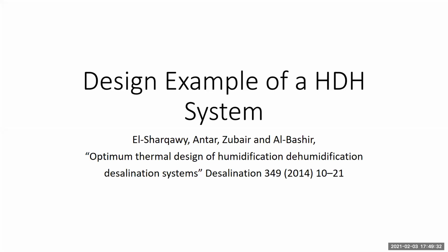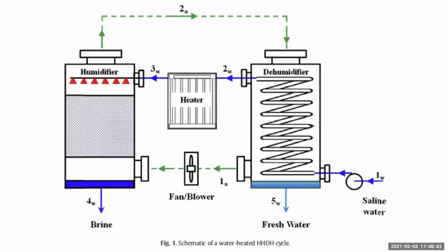Do we need some specific information more? Yeah, we can assume some. We can, for example, say that we are going to rely on low grade energy, so that I'm going to have rejected energy or rejected heat, which is not going to exceed a temperature of 60 degrees centigrade. This is the maximum temperature of the cycle. And the cold water that we have is coming at a temperature of 30 degrees centigrade.